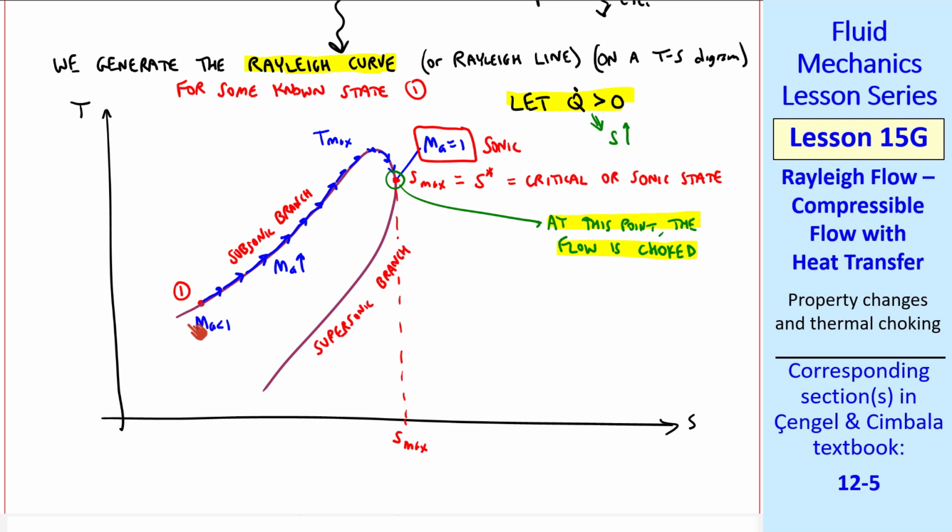Physically, what's happening is if you have flow in a duct starting at condition 1 and you keep adding heat, Mach number keeps increasing until it reaches sonic Mach number 1, and it can go no further. The same thing happens if the flow starts supersonically. In this case, since Mach number is greater than 1, the opposite thing happens. Mach number decreases as you move along the duct when heat is added, again reaching Mach number 1 eventually. You cannot continue backwards on this curve, so again the flow is choked.